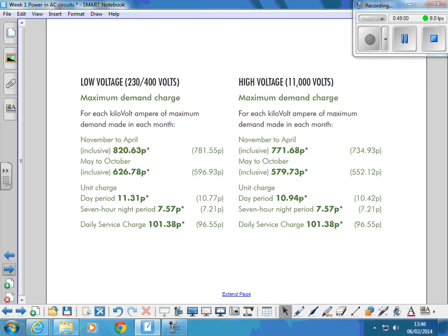We haven't discussed power factor correction yet, but there are two ways of doing it. One is to have it overall on the load centre where your switchboard is. The other is to have it locally, mounted at the point where the motor is, and sometimes both. Usually the load centre equipment is automatic, so it'll switch in and out according to changes in reactive load.